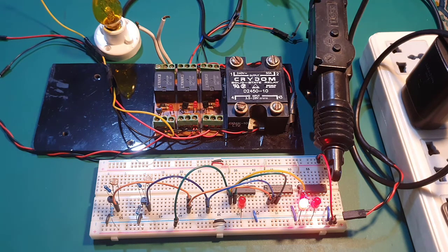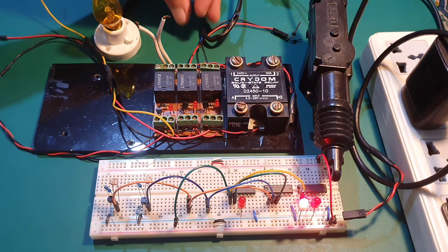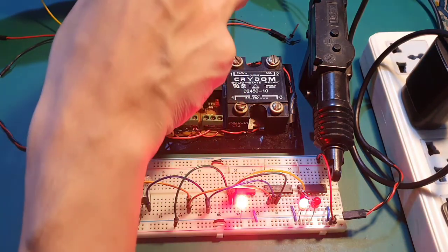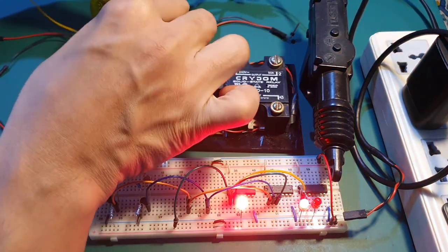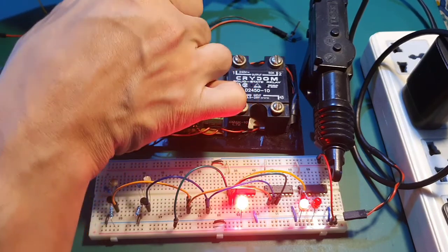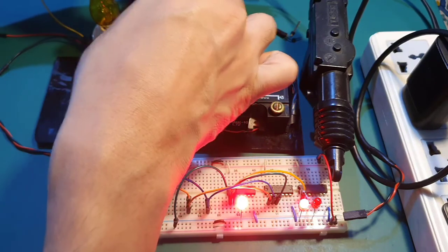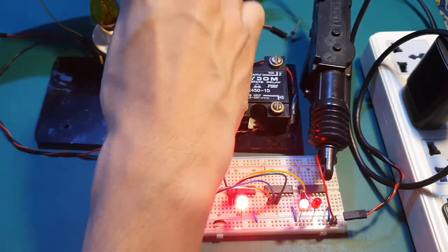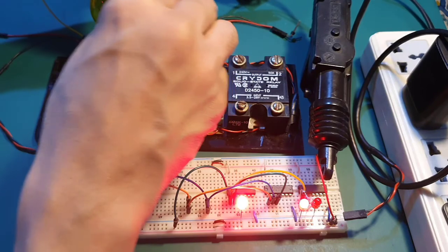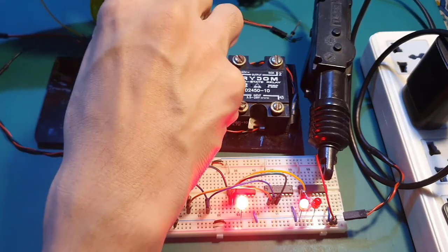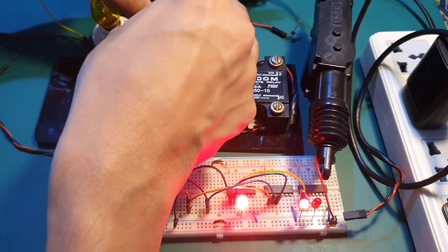So, to cut the story short, we need something that our logic circuit can control, and that can support high current and high voltage to switch these output devices. And that is basically the use of these relays. It can be triggered electronically, and it can drive or switch devices with higher voltage and higher current rating.